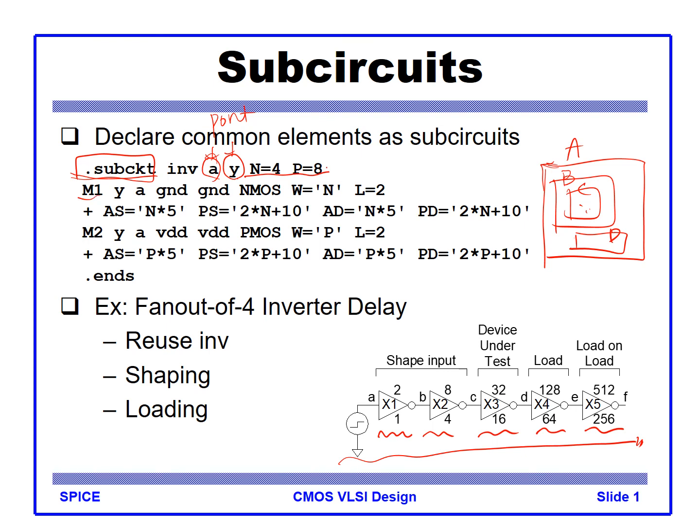Inside the sub-circuit we have M1 and M2. So YA is the network we are seeing, and we get the ports. We have the NMOS and PMOS, and all this kind of information is defined in the sub-circuit, ending with .ends. This is the example of the fan-out-of-4 inverter delay for simulation. So we use the sub-circuit definition.